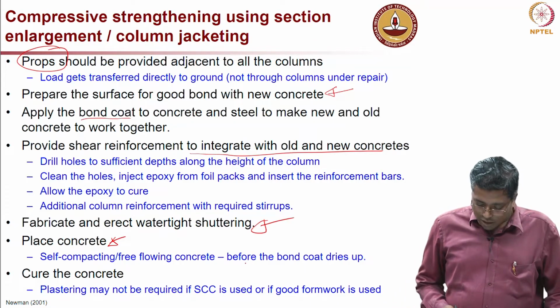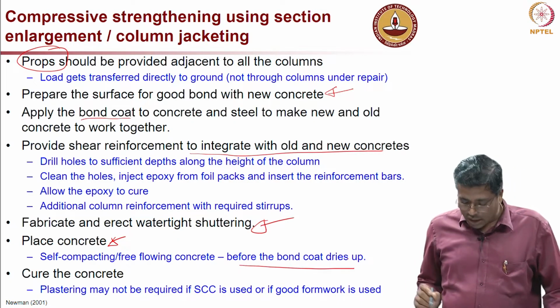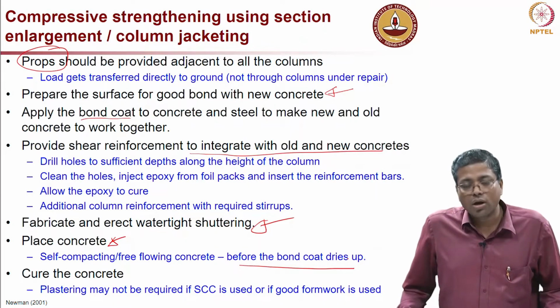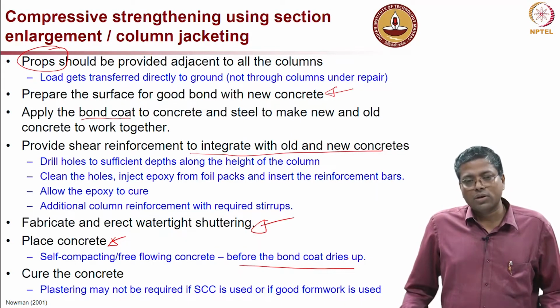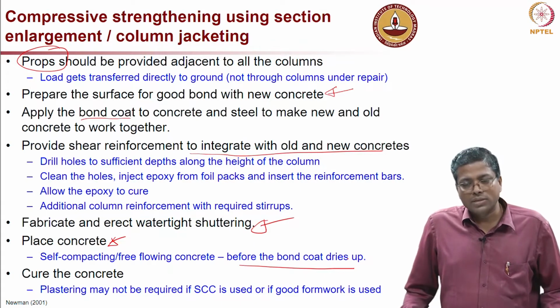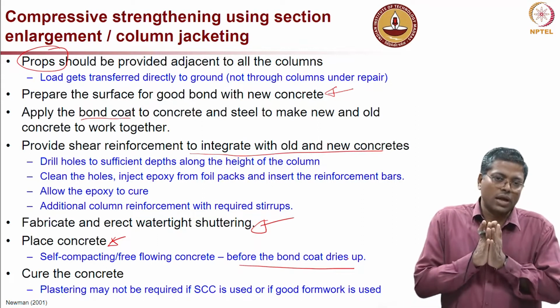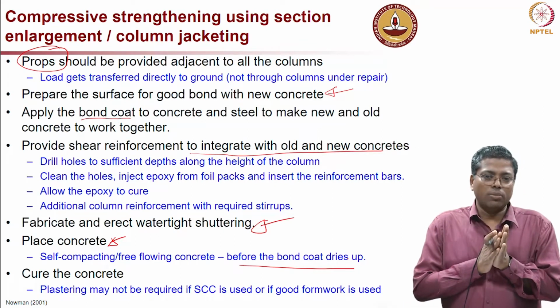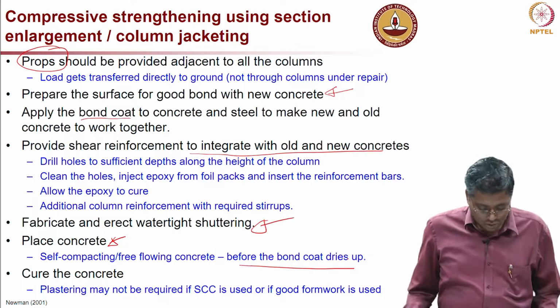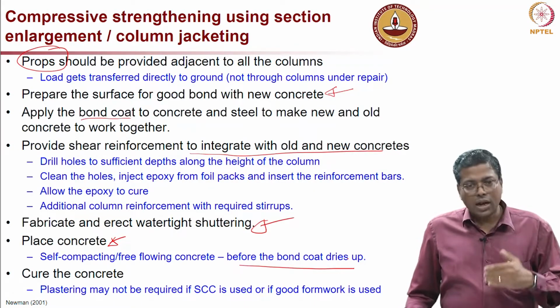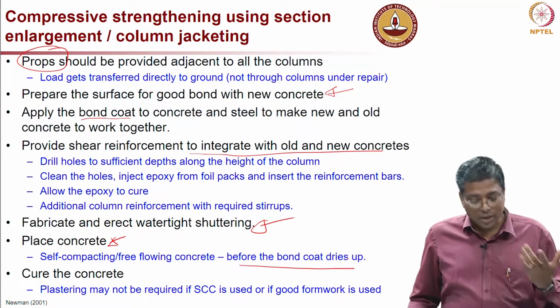Now, one important thing is that the SCC, or micro concrete, or whatever repair concrete you use, should be placed before the drying of the bond coat, then only will proper grip and bond develop. You should not allow the bond coat to dry completely.